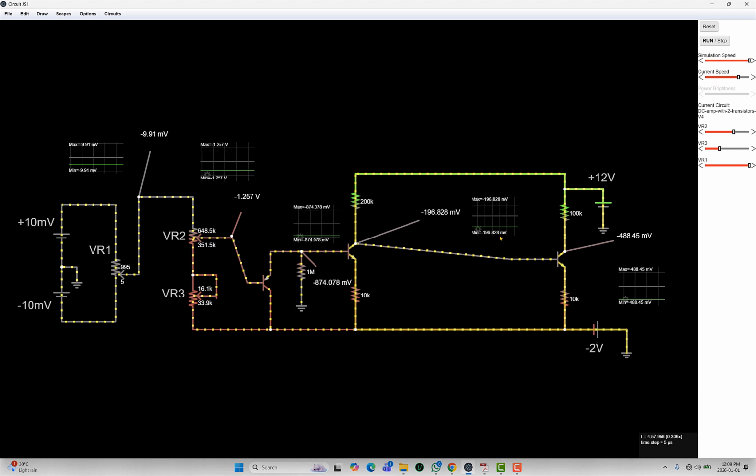And to calibrate things, I could use these 2 pots. So of course my input, I want to go from these 2 ranges. And then this here, this is just a buffer, really. So I guess you might be able to take that out, but maybe it helps because any reflection from the 10K could cause loading. Maybe it'd be minor. It seemed like I needed a pull down resistor to ground, just anything high. I'm not sure in real life if you'd need that or not, but the simulator seemed like I just put a high value here to ground from the emitter. You can't just leave the emitter with really high impedance, I guess.